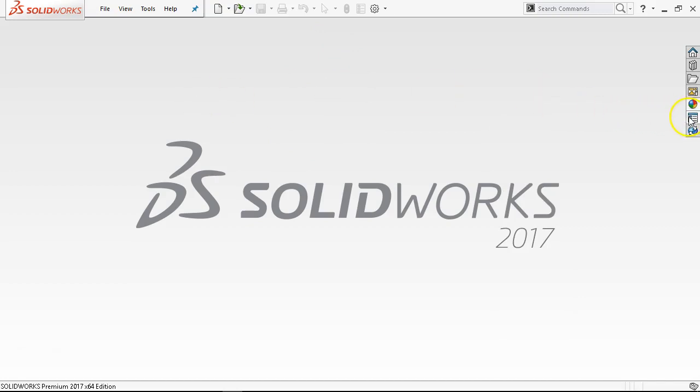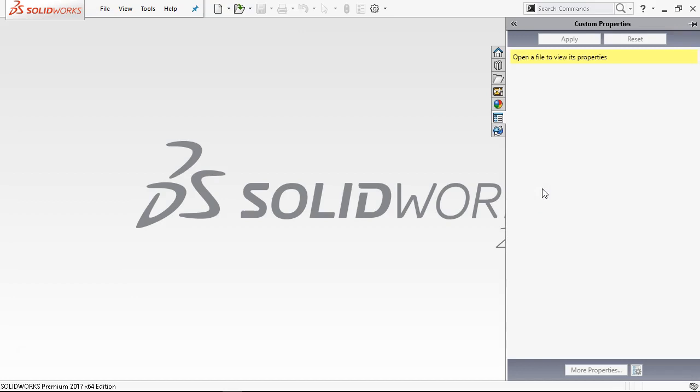All right. Next one down, custom properties. Probably won't have any. Yep, not going to have any for our part that needs to be opened. Part, assembly and drawing can all have custom properties. So since the drawing will populate, we would go to File Properties, or under Custom Properties, we can set up